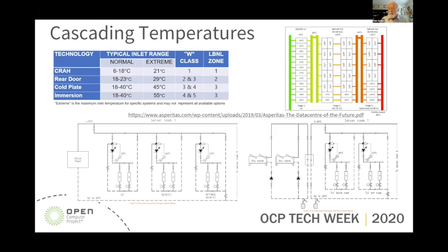And in those cases, the outlet air temperature might be high, which then becomes the inlet temperature of the IT equipment, and the equipment may reduce its clock speed in response. We've chosen to accept that penalty in exchange for reducing the capital costs associated with a compressor-based cooling plant, reducing its complexity, and also improving energy efficiency.